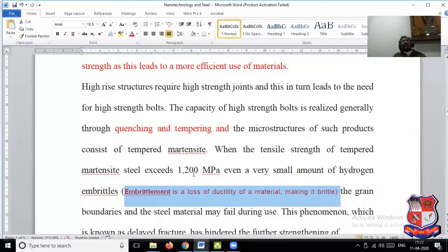So material to material, the story changes, but it is not only trial and error. You have to perform a perfect study, and then you are able to conclude which temperature range is very suitable. After each experiment, you also have to perform a number of characterization techniques such as XRD, SEM, TEM. Based on that, you are able to identify the phase.